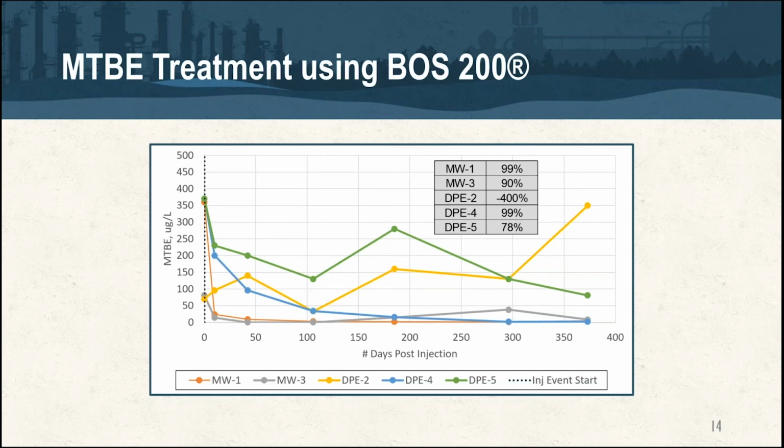But if you've got a relatively low goal for MTBE concentrations, you may have to come back and do some supplemental injection work once all the BTEX compounds and other hydrocarbons have already been dealt with.